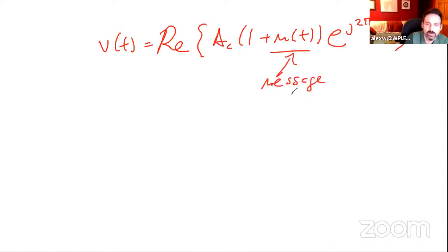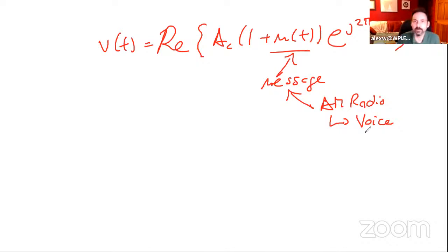And your message, let's say for instance in AM radio, is human speech, it's voice. Human speech, for the most part, we can communicate from 0 to 8 kilohertz. You could truncate that in half and communicate 0 to 4 kilohertz, but your voice is going to sound very muffled. With 8 kilohertz you capture some of the higher frequencies, and it sounds like the voice has more presence. But 4 kilohertz is passable. That's what you see in the old school landline phones. It's very bandwidth conserving.